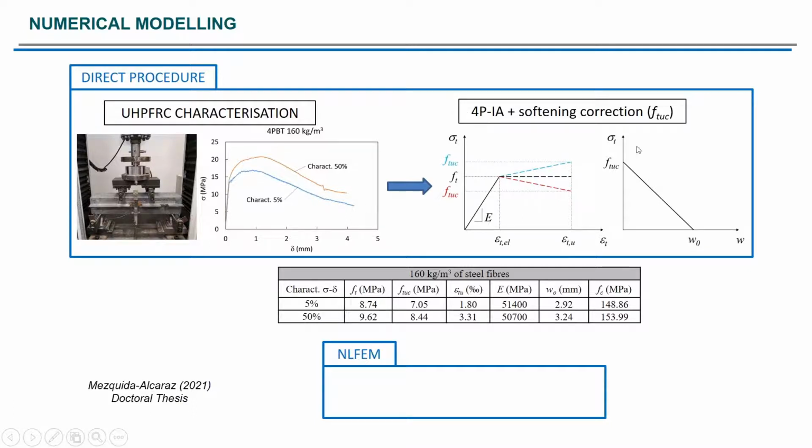But after applying the inverse analysis, as these are tensile properties, the results, for instance for average values, give us an FT value of 0.62 or a strength value of 8.444, which is far less than the equivalent bending stress. And in any case, we are dealing here with a concrete that can be characterized as having a strain softening behavior in tension. Well, with this characterization, we have developed two different models, a 2D model and a 3D model, to characterize these UHPFRC ties.